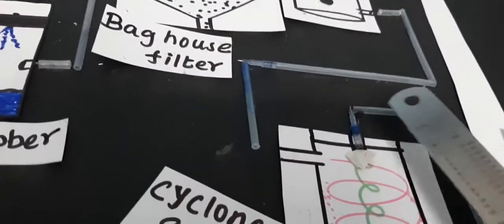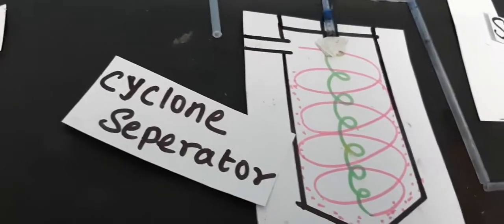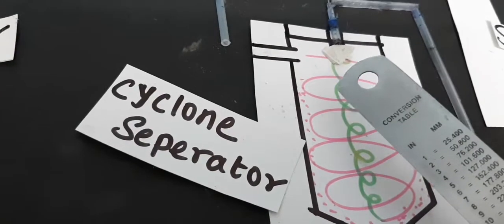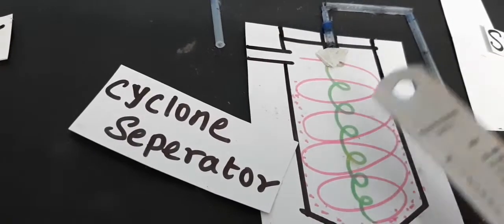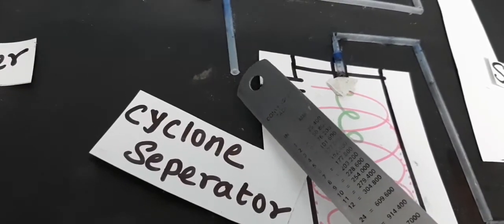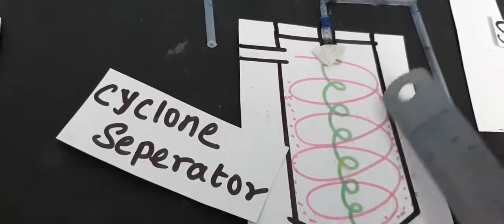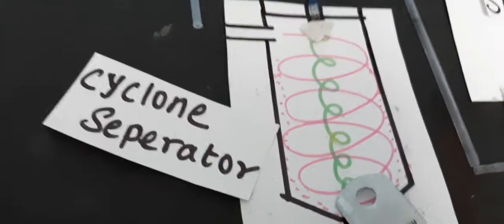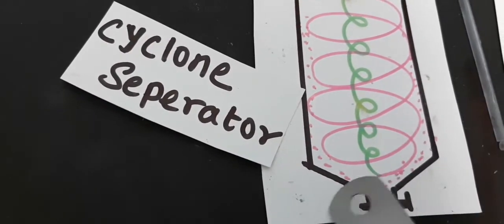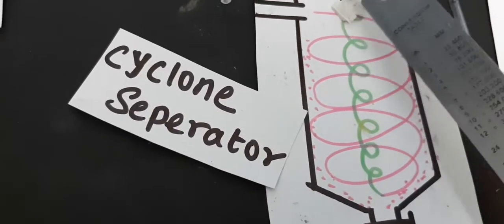And another unit, the cyclone separator. In this case, the particulate pollutants are removed by centrifugal force. First the polluted gas is subjected to a fast spinning motion so that the particulate pollutants are thrown onto the walls of the container and the clean gas is removed at the top.